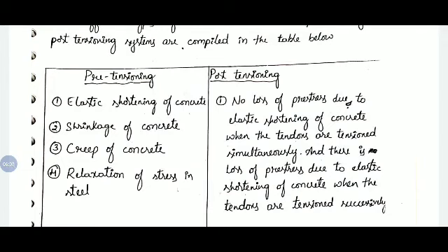Here, for elastic shortening of concrete, we have a condition. If you are providing only one tendon, there will be no elastic shortening of concrete at all.